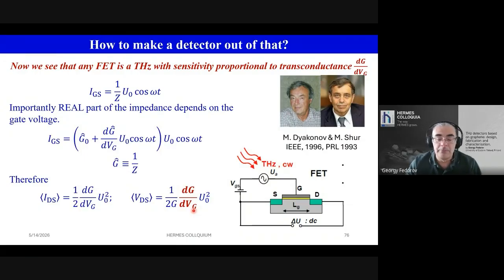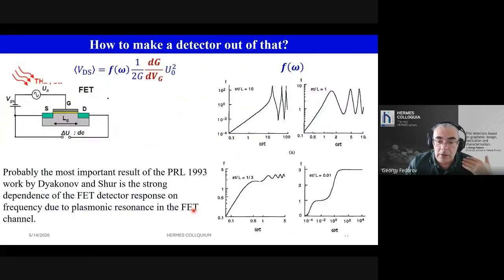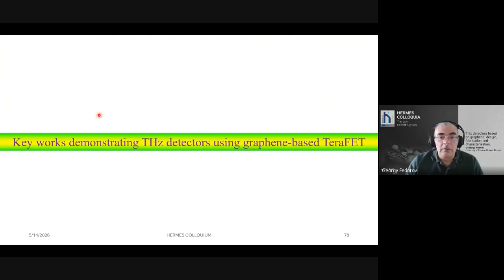and have good sensitivity. Okay, so more importantly here, they predicted that for a high mobility channel, the response will strongly depend on frequency. So it will be resonantly enhanced due to excitation of plasma waves. This effect is important from both fundamental and application points of view.